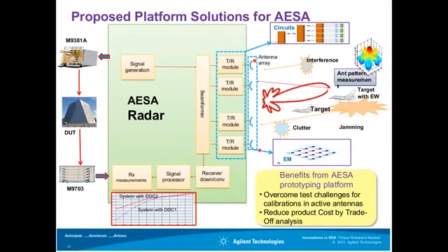For the antenna array, we also allow you to use some EM simulation results. Then for whole system performance monitoring, we have antenna pattern measurement, allowing you to take a look at how the beam and the side lobes are going. Is it satisfied or not? Then we can select the right parameters to do this.